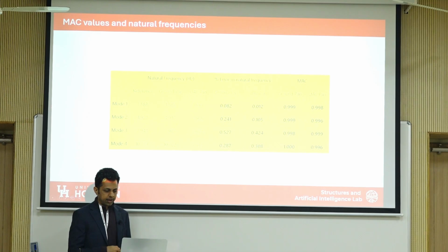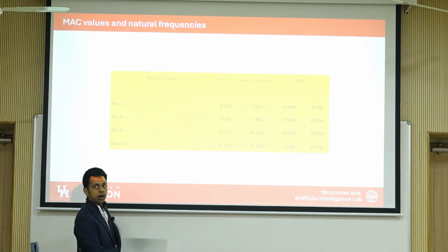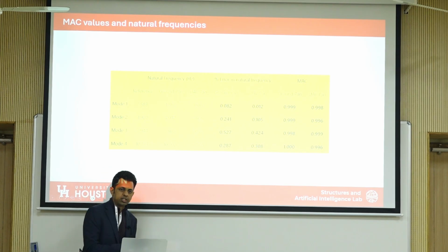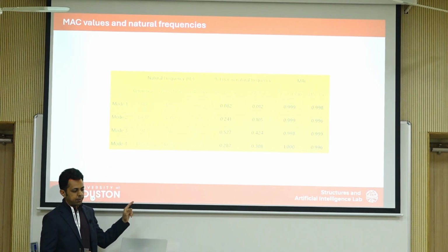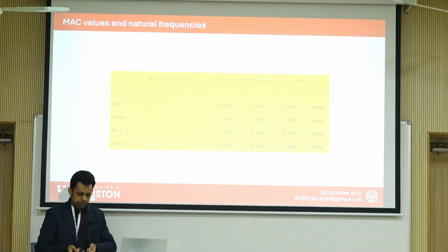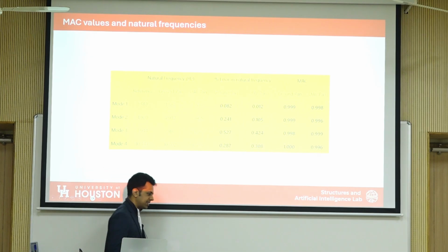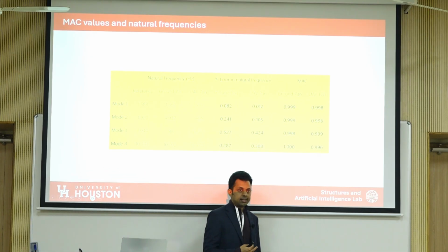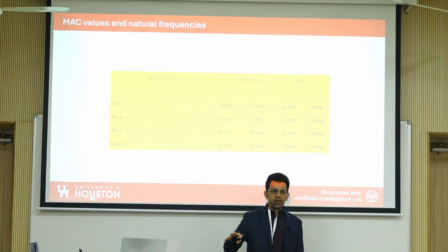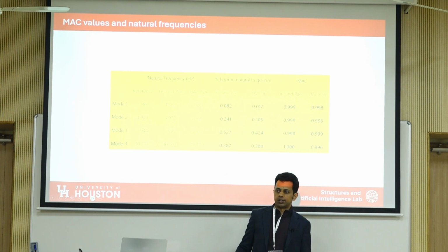And you can see that these are the MAC, modal assurance criteria, which measures the distance between the mode shapes, and you can see that the ground camera panning as well as the UAV panning, they're very close to each other. So the UAV provides, in this case, also a useful tool to acquire information from different parts of the structure.